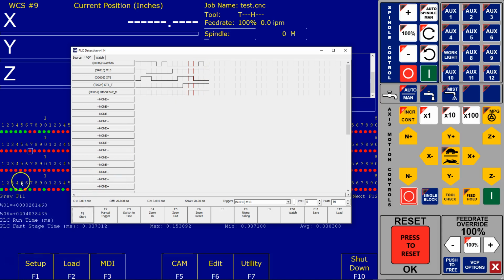So you can definitely use this to pinpoint and figure out what exactly was going on, and why certain things weren't being turned on. The biggest use I've seen for this was for tool changer stuff, where they had various different inputs, and I didn't know what the state of the inputs needed to be for that particular tool changer. So I'd use this logic analyzer, look at those inputs, and force the output on that would move the carousel of the tool changer, and just look at the various states of the inputs.